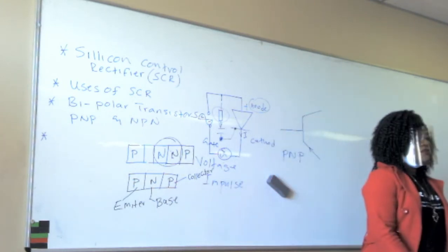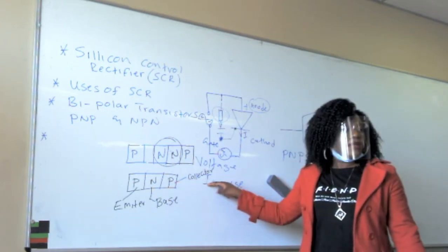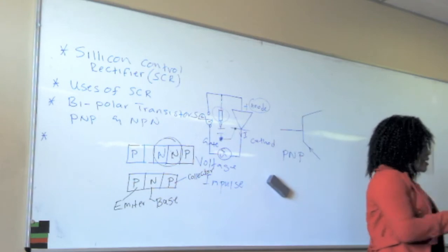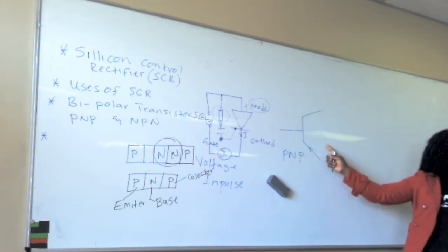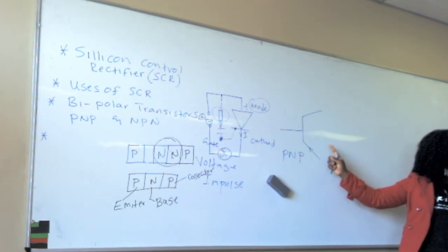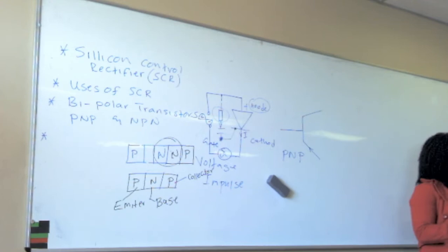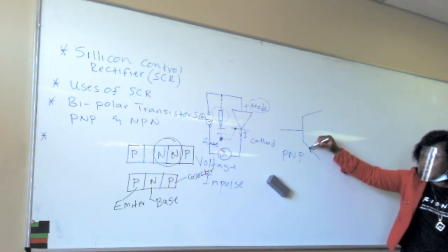They are wires. When I say collector wire, it's a wire that will be connected to the collector side or a collector plate. Looking at this sketch here, this is the electronic symbol of a transistor, which is PNP. What makes it a PNP is the arrow that goes into the transistor.